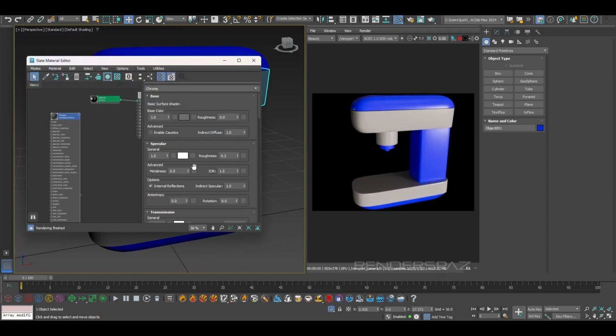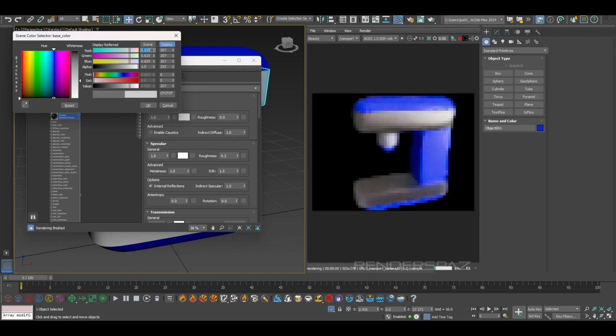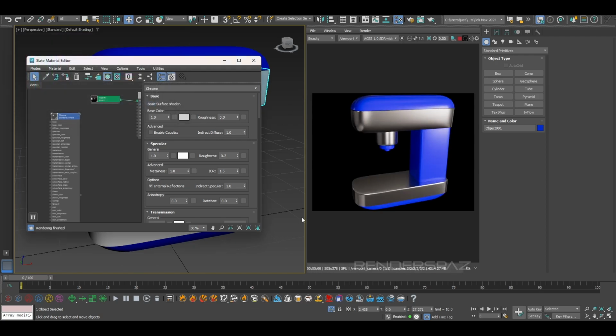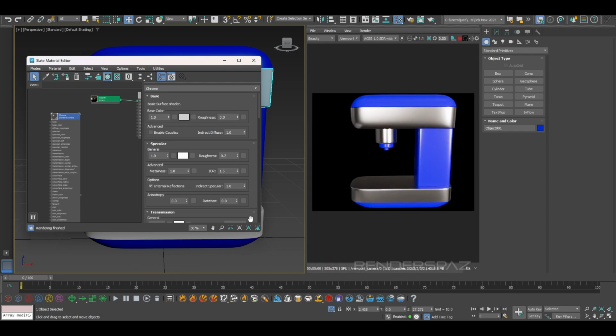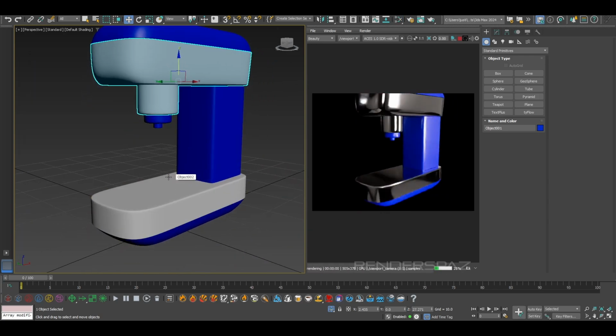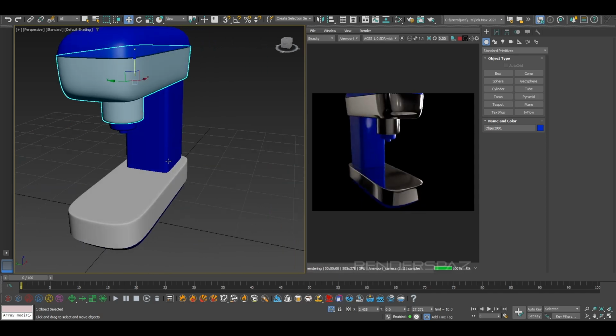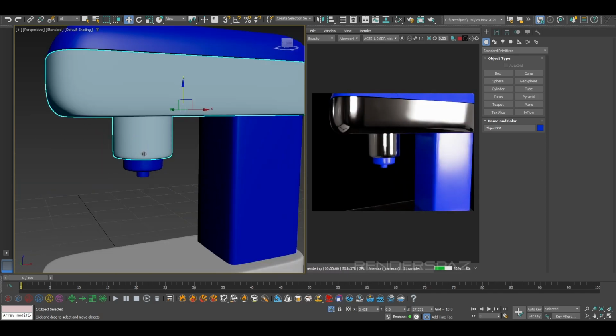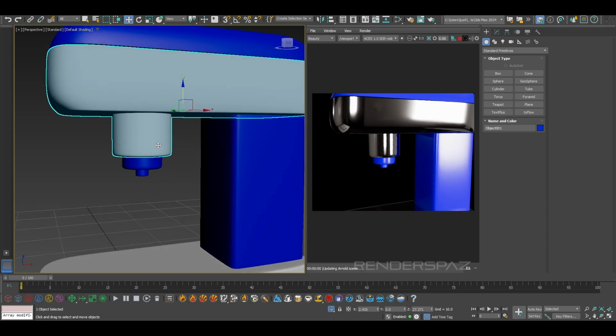I'm just going to create a standard surface material, and then we can bring up our metalness a bit here, and now you can start to see we're getting a little bit more of that chrome look. So we'll get something like this as a start. Alright, we're going to play with the roughness a bit, tighten it up so that it's just a little bit more glossy. Right now it's really taking in a lot of our environment, and the environment is pretty dark, so this really will change based off of your HDRI image. But I believe this will help us for now.